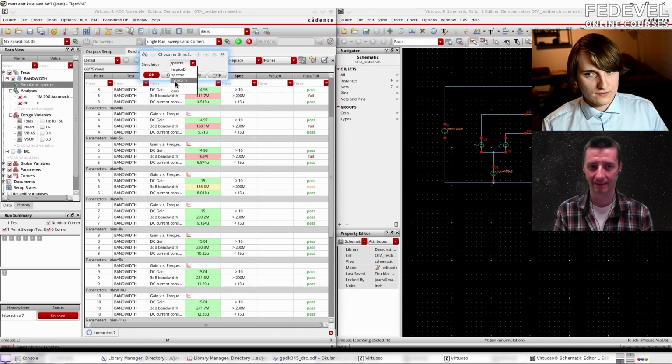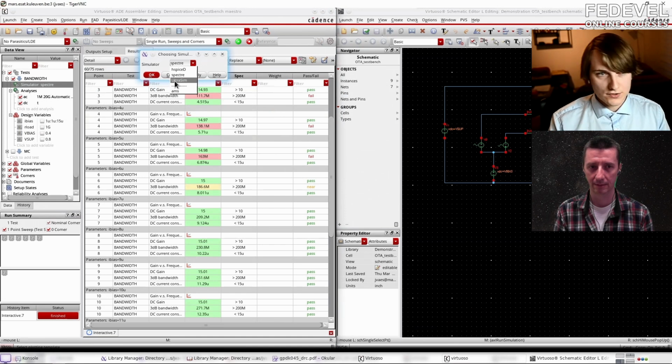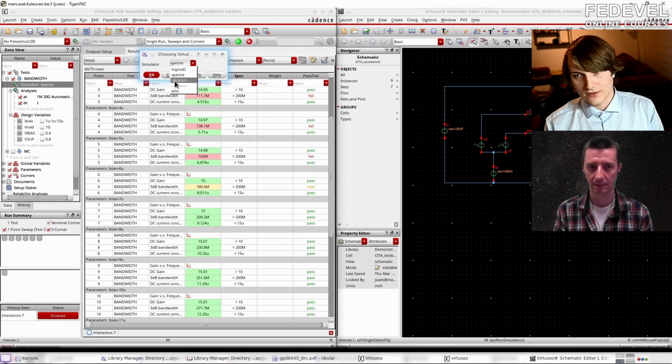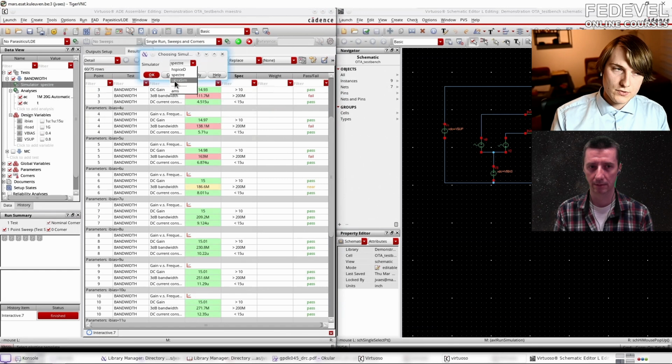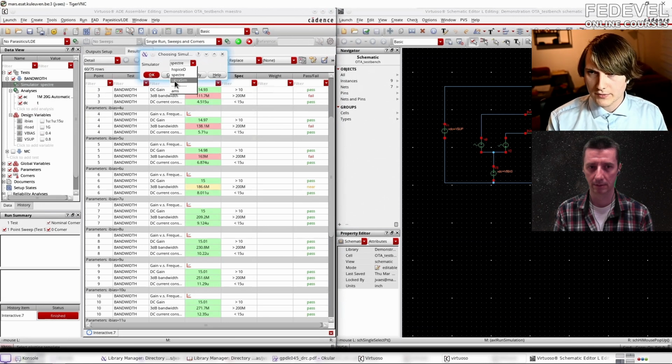So for us, if I'm working in, say, a 14 nanometer FinFET technology, you pay per square millimeter of chip area that you tape out, and we do an MPW. What they do there is they make a very small amount of chips, and they combine lots of designs from different companies all together on one wafer, so it's cheaper. And for us, I think 14 nanometer is $24,000 per square millimeter, and then we get 100 samples.